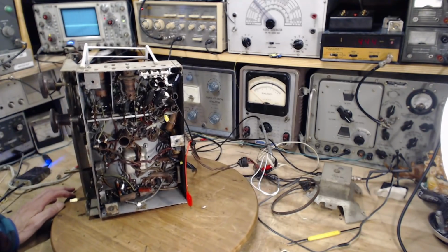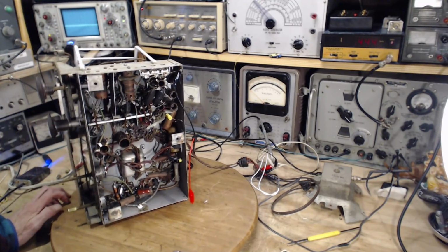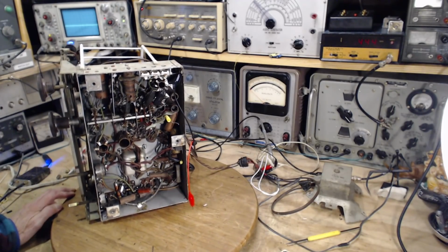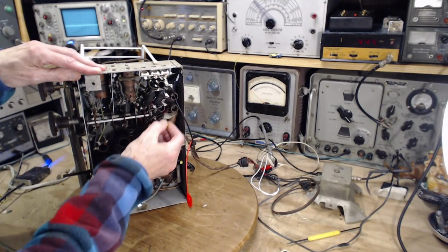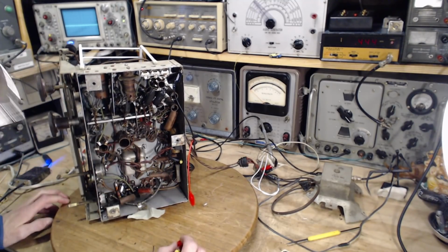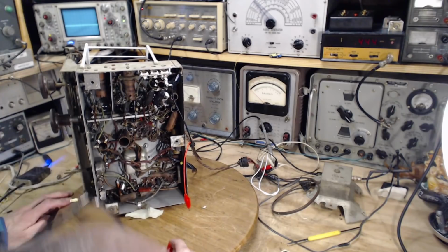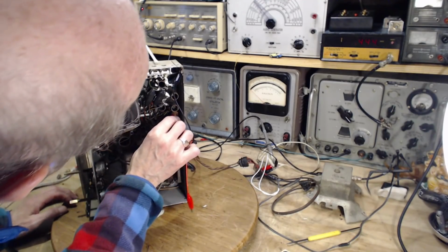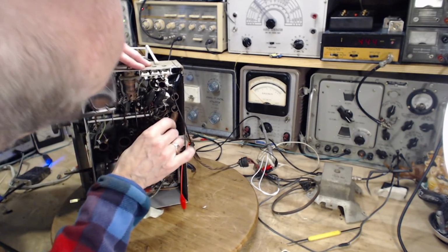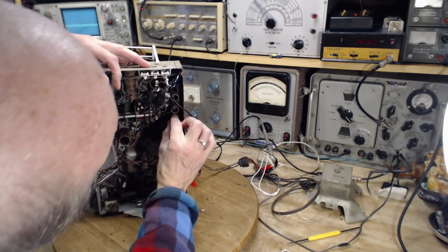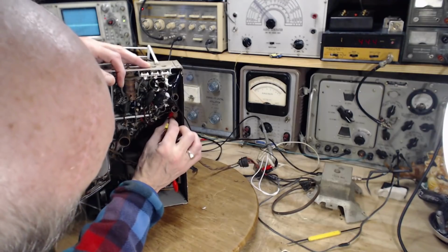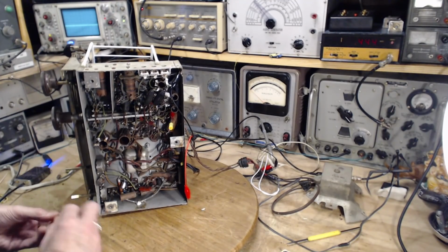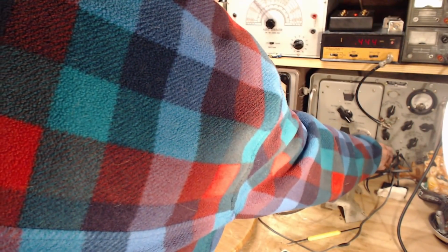That looks good. And is that really pin 8? I don't think so. No, it's not pin 8. That's pin 7. Pin 8 has a green wire on it. Green wires are often grid wires. Let's see if I can get in there. That's good. No chance of shorting. Okay, turn down the output here.